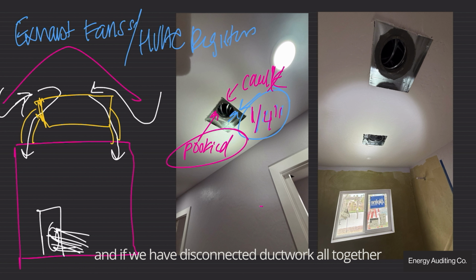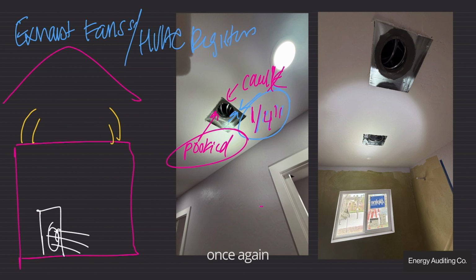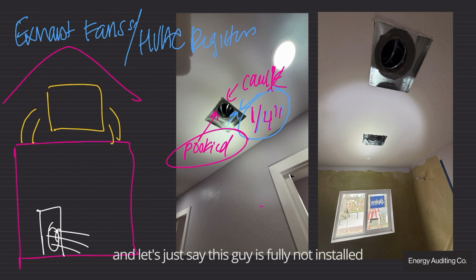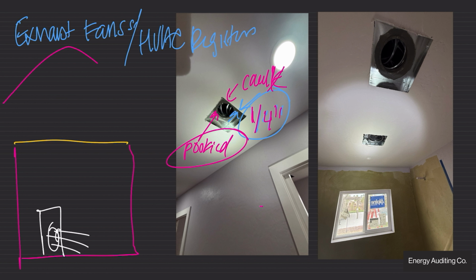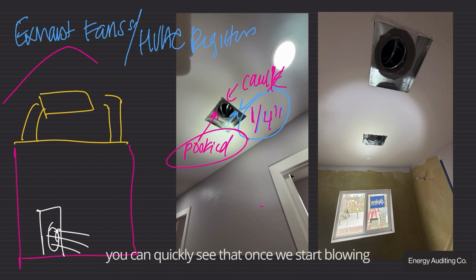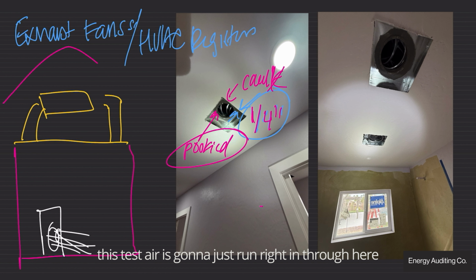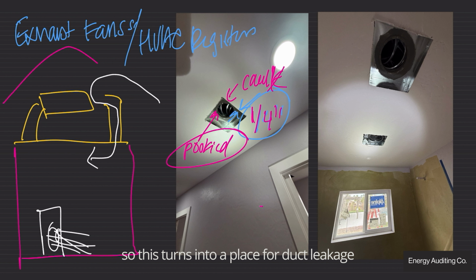And if we have disconnected ductwork altogether, what'll happen? We have that, and let's just say this guy is fully not installed. We have a duct running here, and then we have a duct that should be installed, but it never made the connection all the way. Once again, you can quickly see that once we start blowing this test, air is going to just run right in through here and into the home. And we do not want that. So this turns into a place for duct leakage.